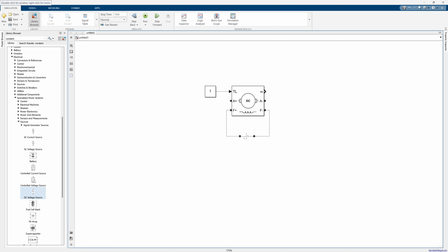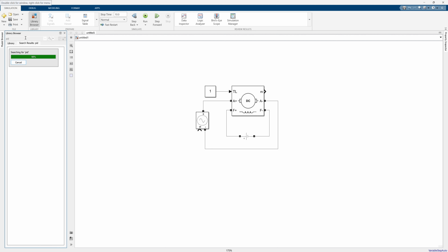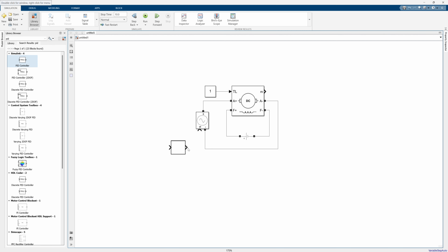And for that, first we need a voltage controller here. So the voltage controller has the inputs like here. We can also add the AC voltage, but this one is the controller. So here we have the input of this voltage controller. Easily, we should apply the PID here to control this voltage. Then we'll control the armature voltage, and then we will have the required value. So we need one PID controlling here.